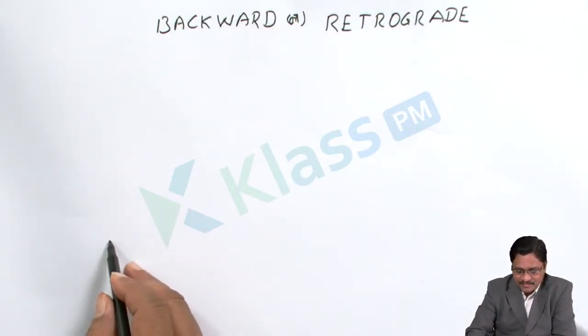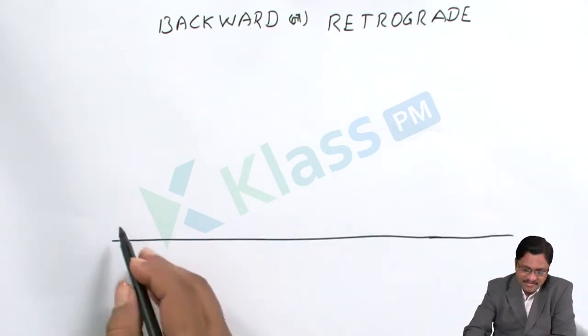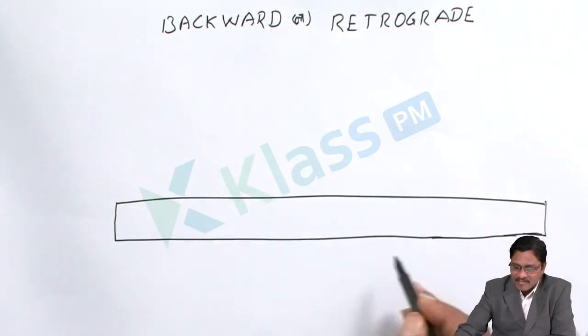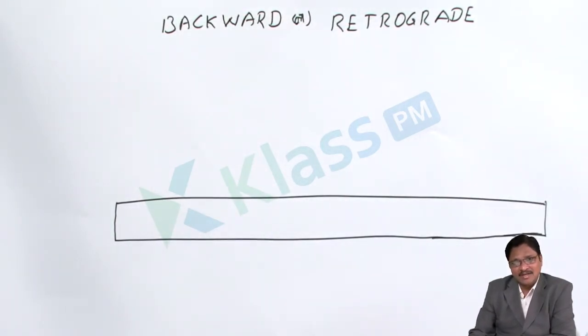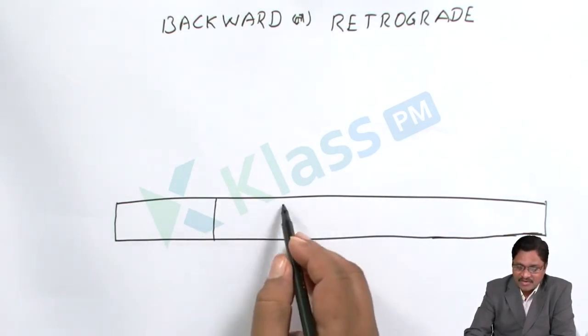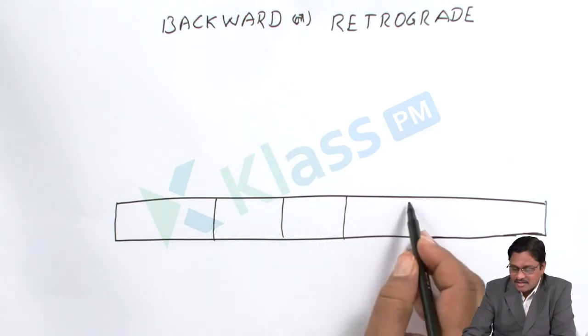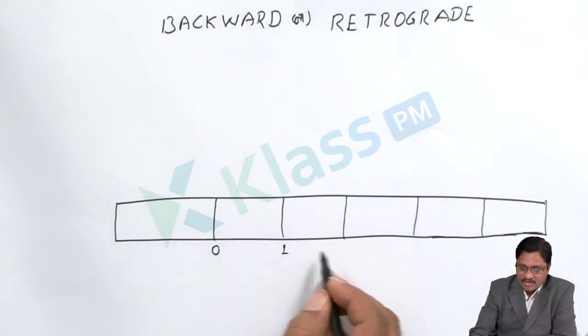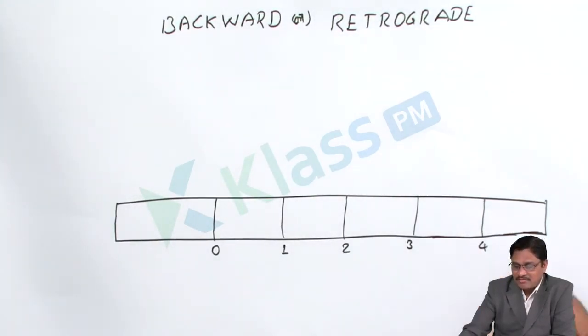So draw here 15 centimeters of length, 1 centimeter width. It has to be subdivided by the same method. You can check on your practice, but you have to apply the geometrical division method. So I have to divide into 10, 6 meters representing 6 divisions. 1, 2, 3, 4, 5, 6. 0, 1, 2, 3, 4, 5. What are the units? Being meters, write meters.